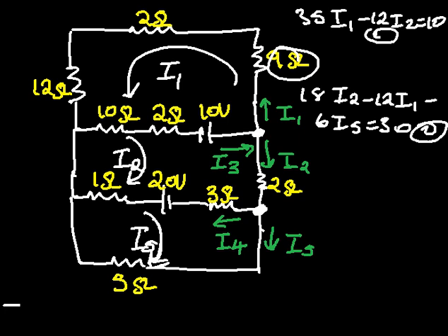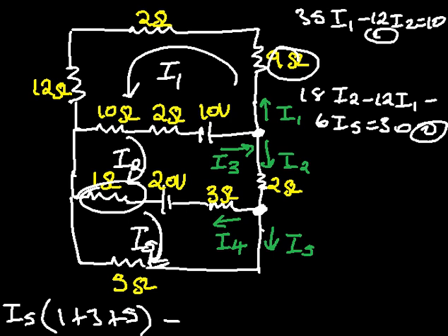We have the current flow, that is I5. And what are the resistors there? We have 1 plus 3. Always need to add here. Plus 5. Minus, do we have any resistor which is being traversed by the current of the other loop? We have, that is resistor 1 as well as 3. And we have minus I2